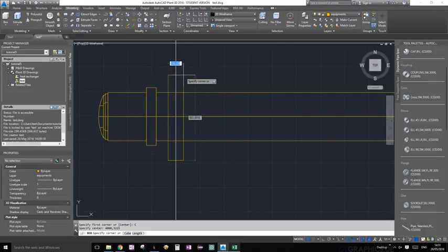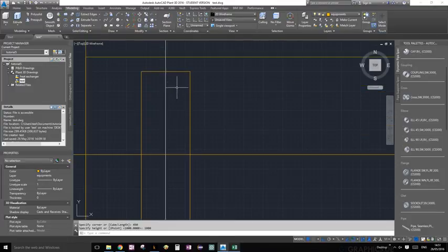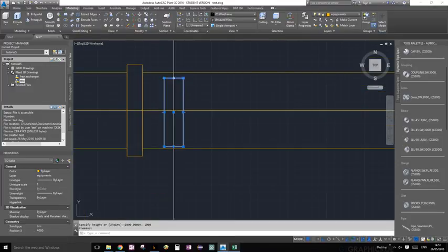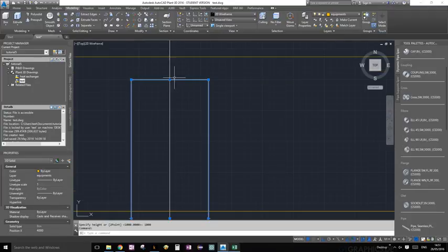First it's going to ask you for the width, so we're going to call the width 125. Why not 125 millimeters? Press tab, don't press enter, press tab, and the length. We know our diameter for our heat exchanger is 500, so let's make it 450. Then it's going to ask you for height. Let's make it 1000. Perfect. Now as you can see, because we didn't have an exact location, it doesn't look quite right, but like I said, you would probably do the support first, and you would know the exact location on an actual design.